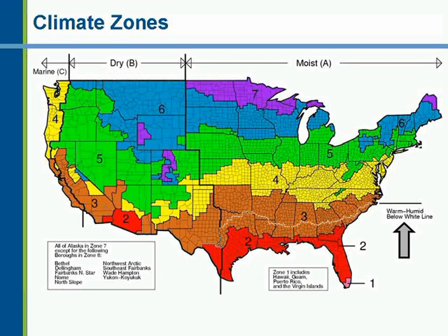As you can see from the numbered zones on the map here, there are 8 temperature-oriented zones. The bottom tip of Florida you see is climate zone 1, and as the numbers go up, you move generally north over on the east side of the United States. That general south to north variation kind of breaks down in the mountain states, but still the 8 climate zones relate to temperature. Those are crossed with 3 moisture regimes.